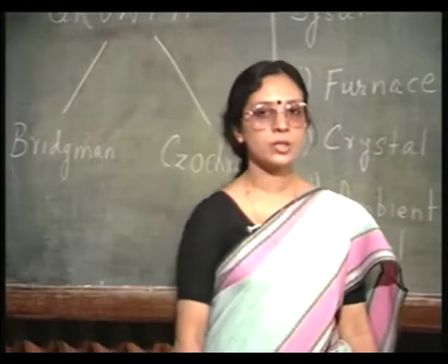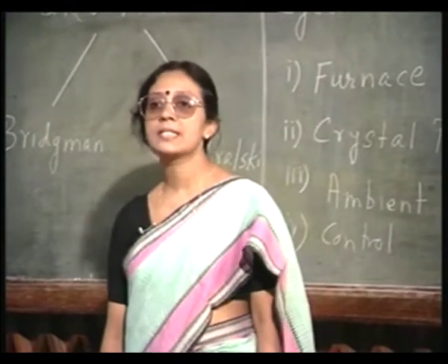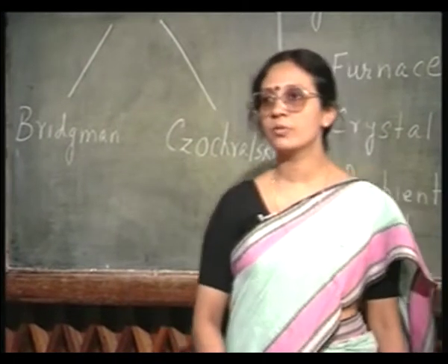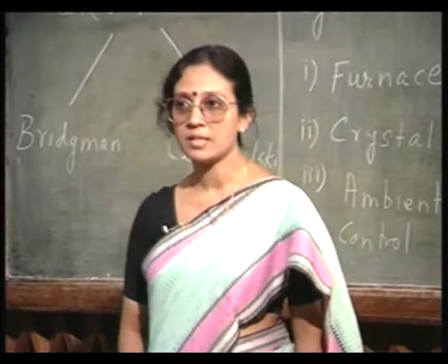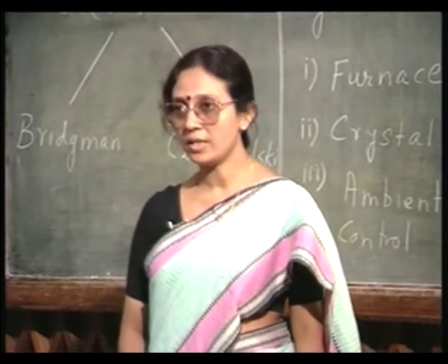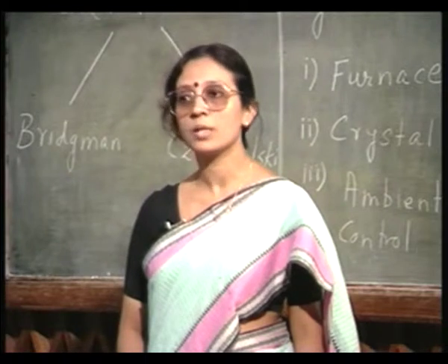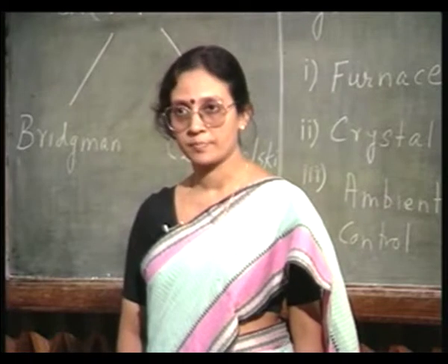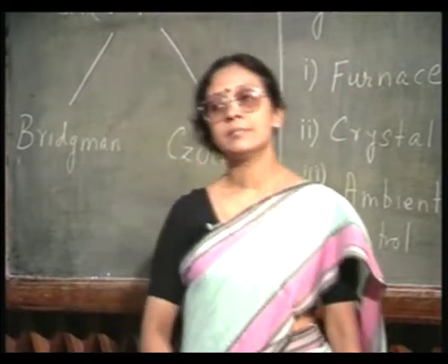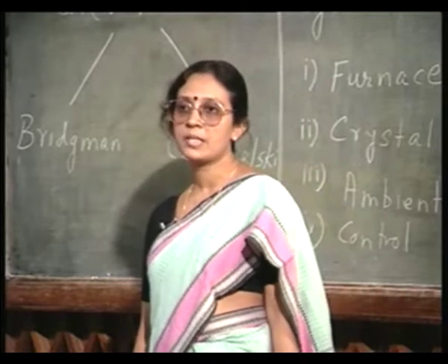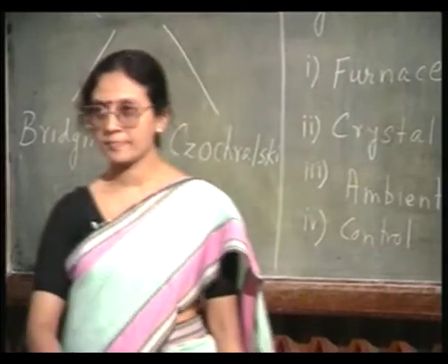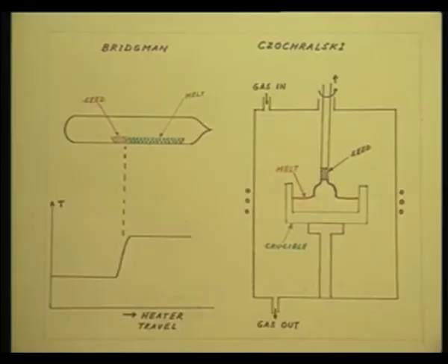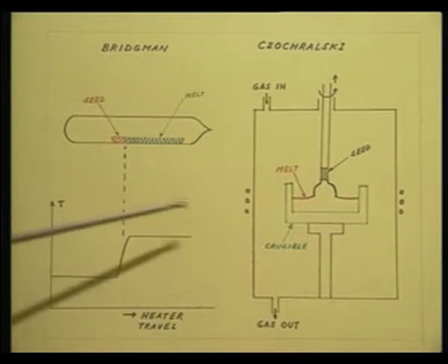And this quartz crucible is usually placed inside a graphite susceptor. A susceptor, you can view it as an outer jacket, that is I have a bigger cup of graphite in which I am going to place the quartz cup. The quartz cup is called the crucible, the graphite cup is called the susceptor. And the graphite susceptor is placed on a heater, usually a very high purity graphite heater, and the heating is usually done by RF.